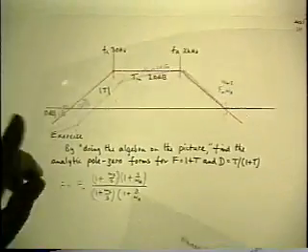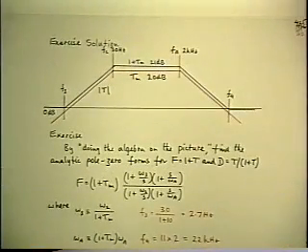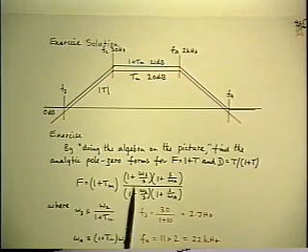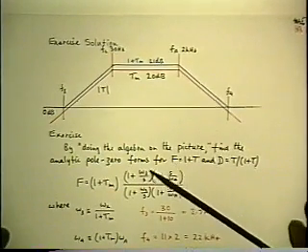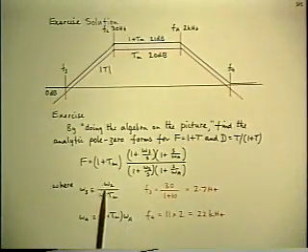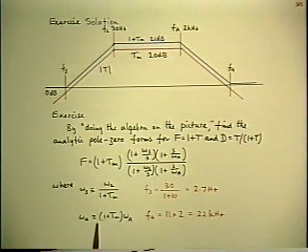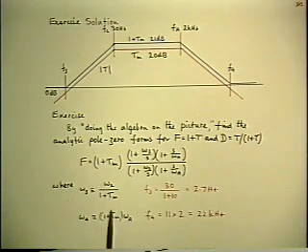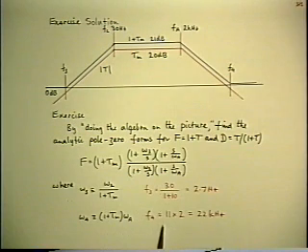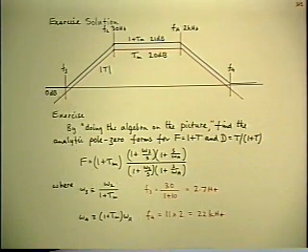And here's the neater version that's already been drawn. Same thing, where I've listed underneath the expression the definitions of the new corner frequencies that have shown up as part of the construction, which is a pair of zeros. And evaluating them numerically, the 0 at the bottom end is 2.7 hertz, the 0 at the top end is 22 kilohertz.